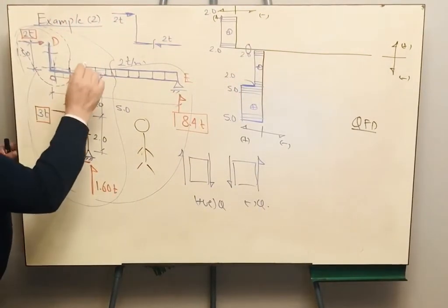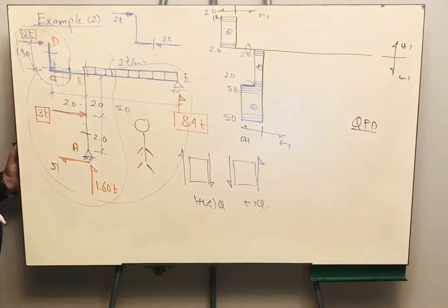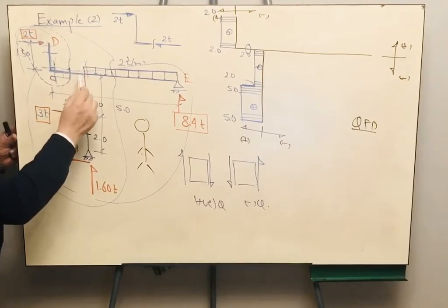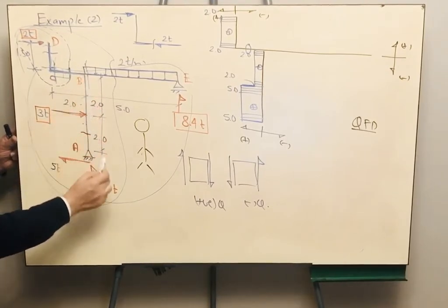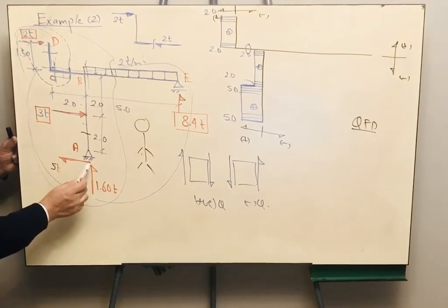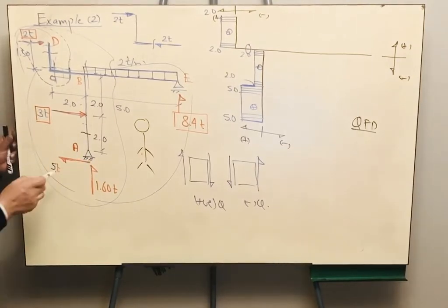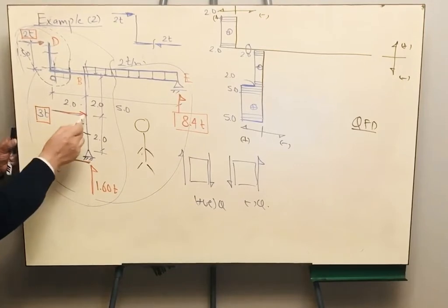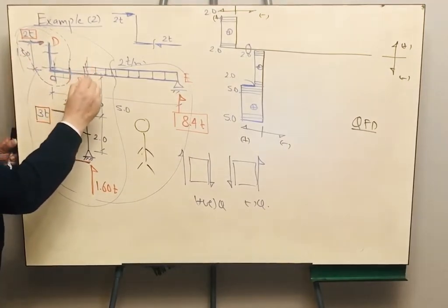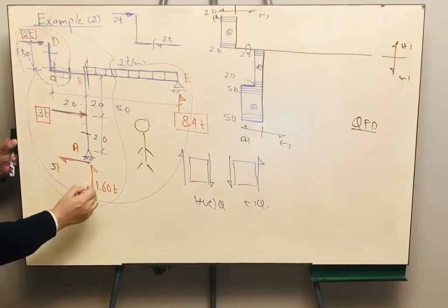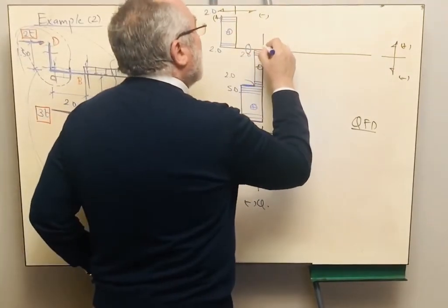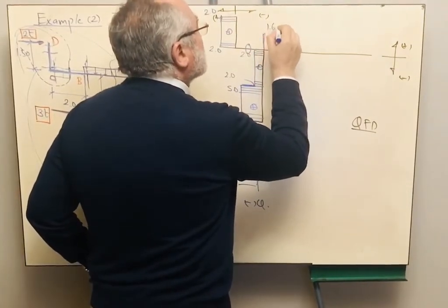Okay. If you are cutting a section here like this, I want to determine the shear right of point B. I will take all of this portion. So I'm having the 1.6 upward and I don't have anything else, because this is not causing shear, this is not causing shear, and this is not causing shear. I'm looking for the force perpendicular to the central line. The only force that I have is the 1.6, which means that I'm having here an upward force of 1.6.